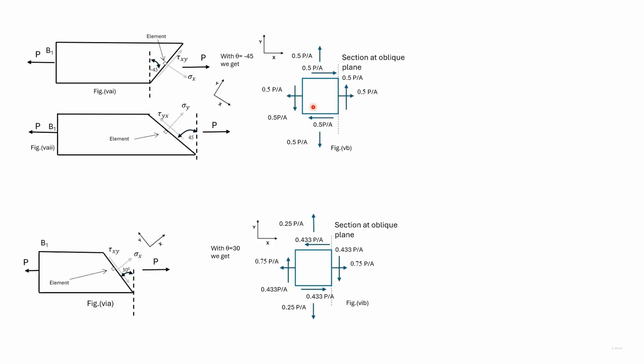As earlier, considering equilibrium, the stress on the other face has to be the same, and the shear stress also has to be equal. These two shear stresses cause a couple which must be balanced by an opposite couple, which is comprised of tau yx. We earlier found out that tau xy is equal to tau yx in magnitude. So we have all these stresses except sigma y.